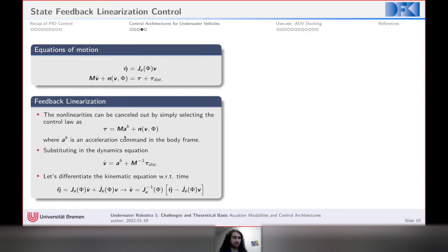And then in the end, if you multiply the mass matrix by its transpose from the left, you also get rid of the mass matrix. This is basically what we get in the end. The system dynamics is what we try to control, the acceleration of the system, by just giving an acceleration command. So we're just controlling a linear system plus some disturbances that we also try to reduce a little bit by inverting the mass matrix.